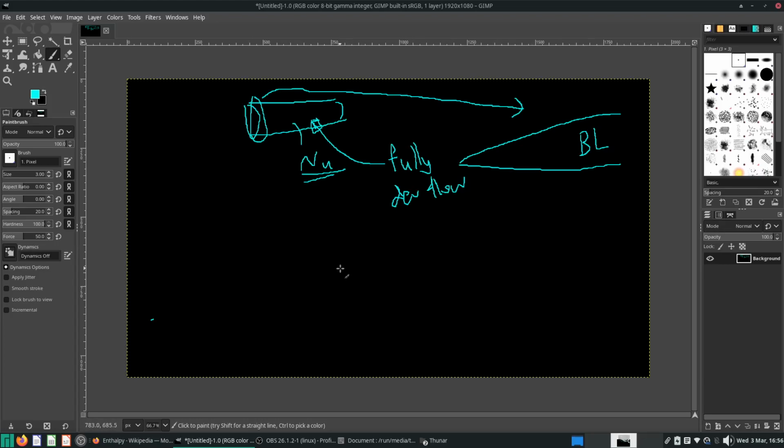This is important because you want to know roughly how effective heat transfer is, maybe across a fin. So you have some fluid with some velocity U infinity and temperature T infinity flowing across a fin. It will create a boundary layer. This is a fin at maybe a constant temperature or some other condition.